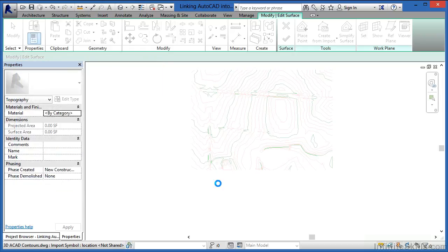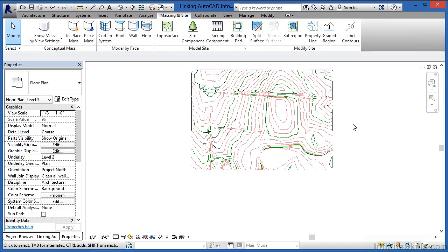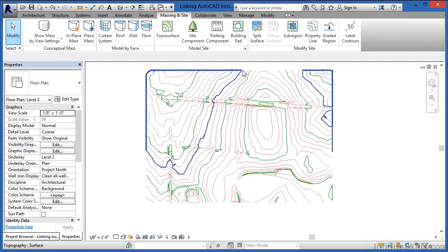few seconds because it's currently converting this into a Revit site. Whenever it's finished this process, click on the big green check mark. Now it sort of looks cut off, but the reasoning is that only some of this site is currently going through our current level. If we went to a different level, we'd be able to see different parts of the site instead.